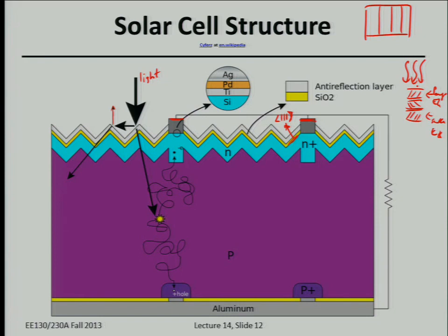So I guess the question is, why would you only form ohmic contacts in certain regions on the backside? Because in principle, you could form this whole backside as P+, right? Oh yeah, that's a good point. So typically, let's say light shines through, and depending on whether it's single crystalline silicon, the cell can be hundreds of microns thick.